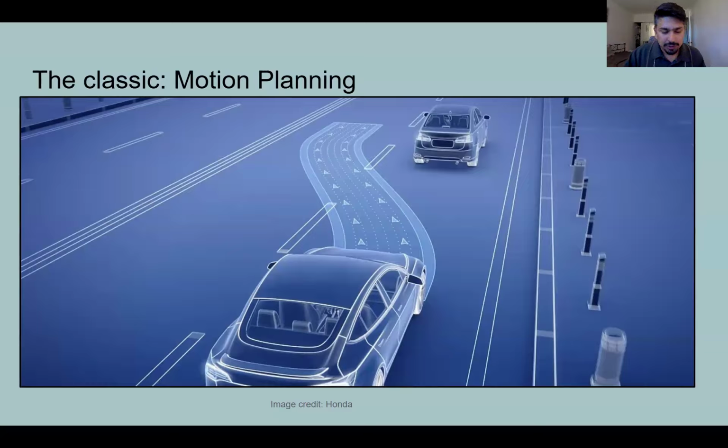Its job is to create the waypoints and trajectories which are safe, and it is doing its own whole optimization problem, because the high level behavior just says we need to do a lane change, but not how we are going to do it, how fast, or where. I hope that makes sense.